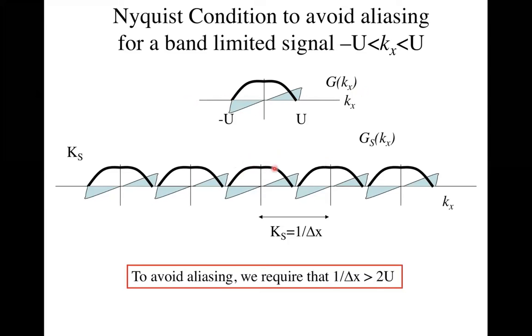And so here's the continuous-valued Fourier transform G(kx). We have sampled such that the repeat of G(kx), which is part of this sampled version of the Fourier transform, if the frequencies come down to 0 before they overlap, then this representation of the Fourier transform is not corrupted at all by these replicants.